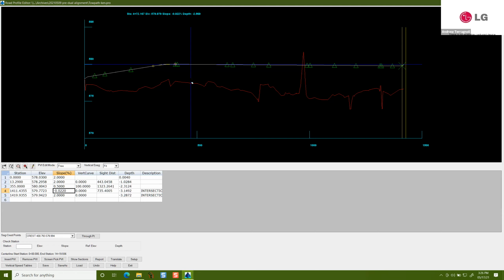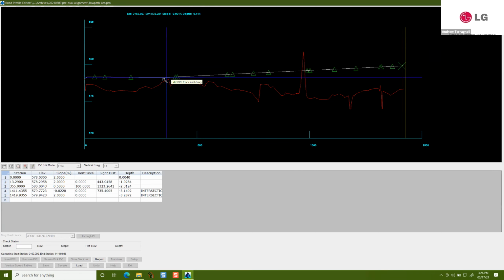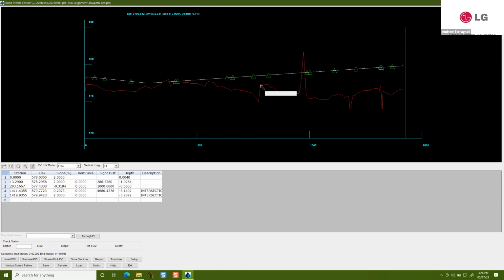Because what are we looking at for depths in here? Well, not very deep. It's like 2.5, maybe 3 feet. Right, there's 3 feet. So it's not terribly deep. I might have to rethink the whole thing. I could save myself some wetland disturbance. I'm already on the fringe. I can't go above a half acre, and I'm at 0.49. So I could buy myself some comfort by doing something like you're doing right now with that vertical curve.